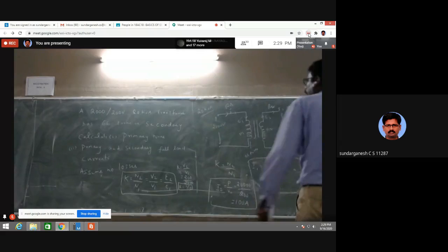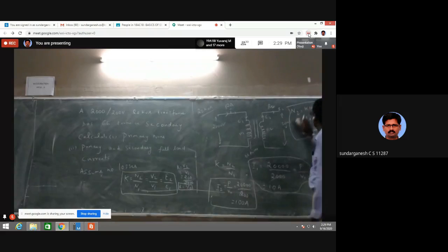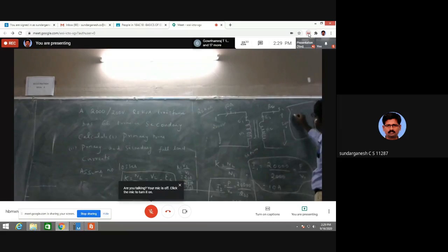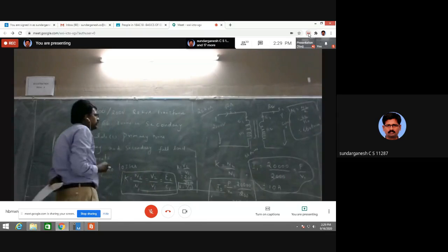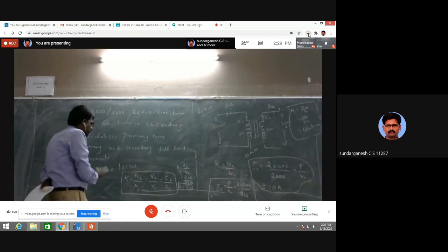So I have to find the primary turns. K is N2 by N1, and I want to find N1. So N1 equals N2 by K. N2 is 66 divided by 1 by 10, which is 660 turns. So it is given that the secondary has 66 turns, and I have to find the primary.